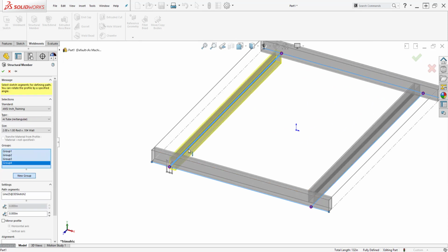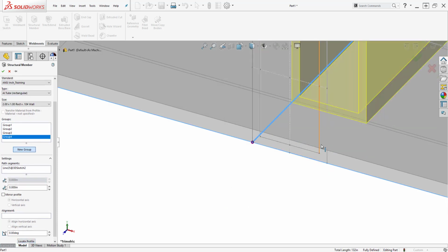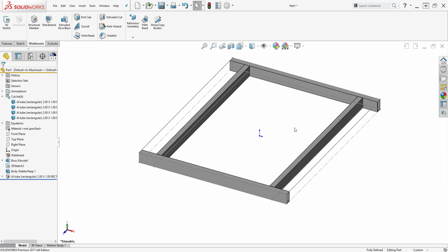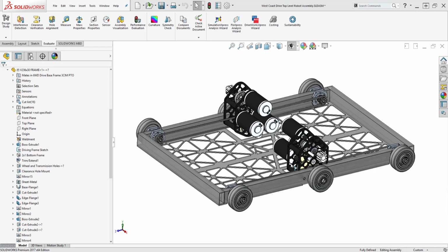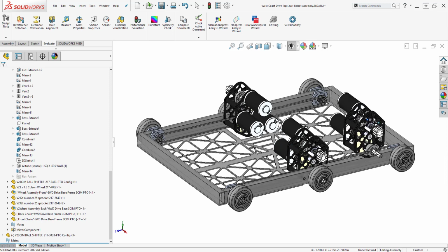Now, it is important to note that at this phase, we know how many wheels and what gearbox we're going to be using, so we can immediately start placing the parts. Placing the gearbox first is going to help you with the rest of the robot components. For this example, we're going to place our West Coast Products dual speed gearbox in the middle, but you can place it in the rear or the front of the robot to accommodate other designs.